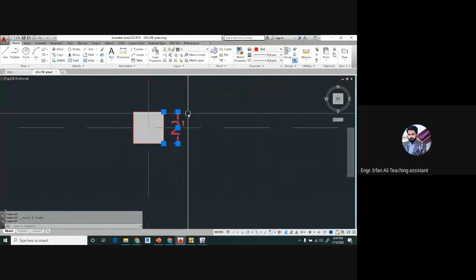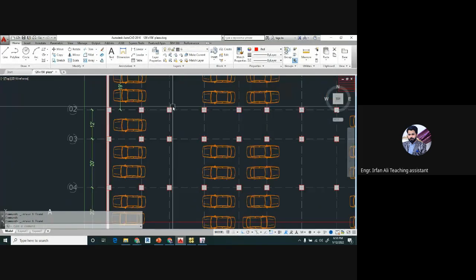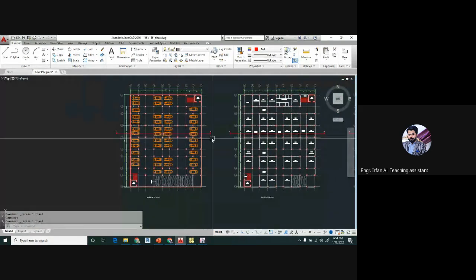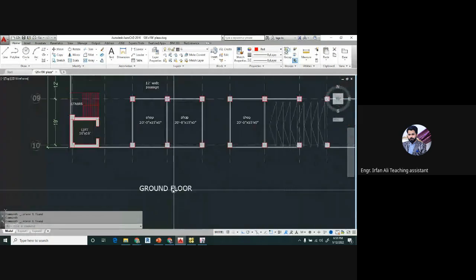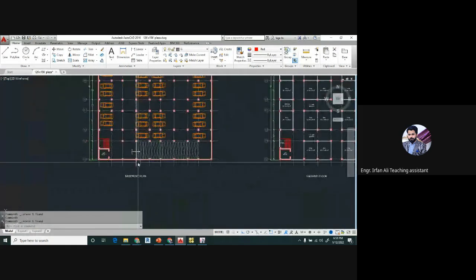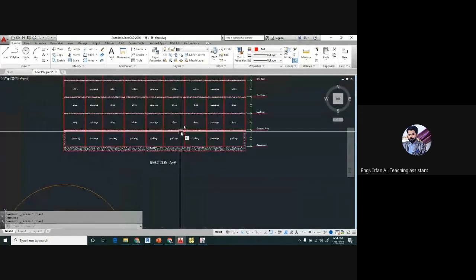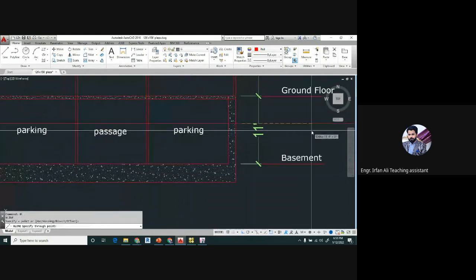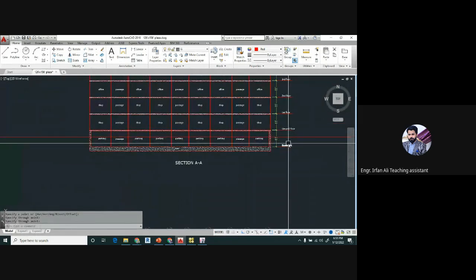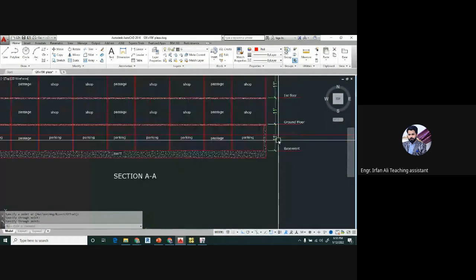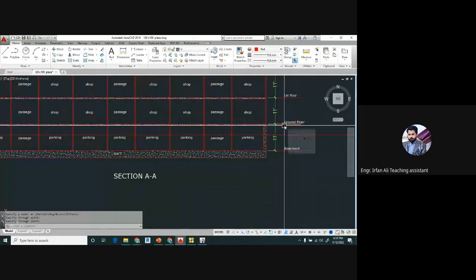So please adjust this according to architecture demand, right? This is the basement plan, and then we have our ground floor. Remember that we are seeing a basement plan. For example, if you make a cut at this level, at the lintel level, you are seeing what is below this line, right? So the slab of the basement floor is the ground floor, right?